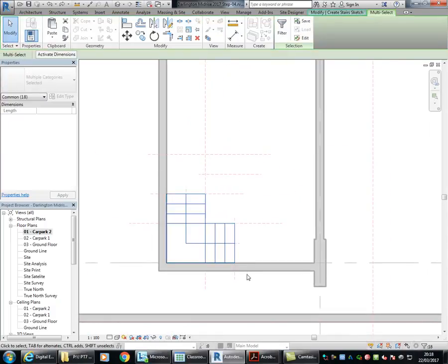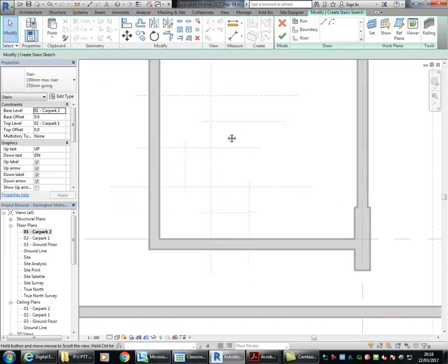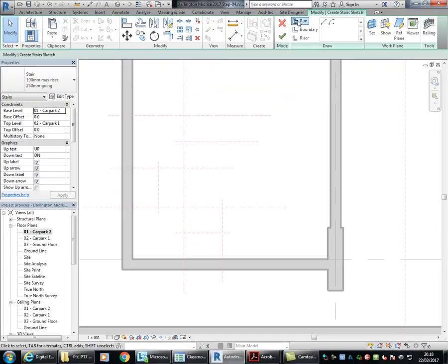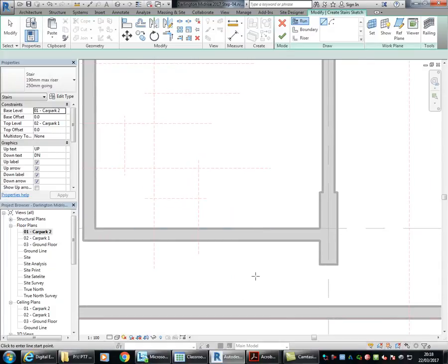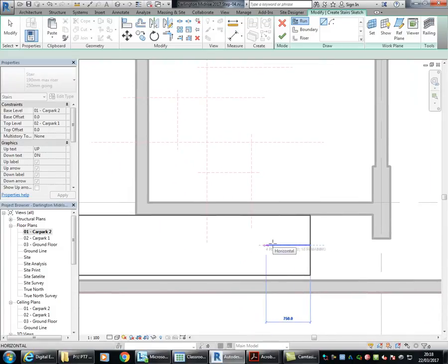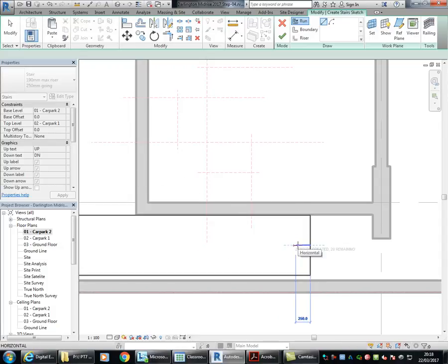So that process though is generally going to work pretty well. But like I said, I was going to show you how you can do it without that first step worked out. So still just with the centre lines, I can go and draw with the run tool and start anywhere. So it's a really good trick, a bit like the ramp. I can just start it over an empty space here. Taking it to the left, I'm just going to start one step at a time. See how as I move the cursor, it's snapping one tread, and it's telling me, if you can read it, oh yeah, it's easier on the decorator one. 2 risers created, 20 remaining. And so as I move, it's going to adjust that count accordingly.